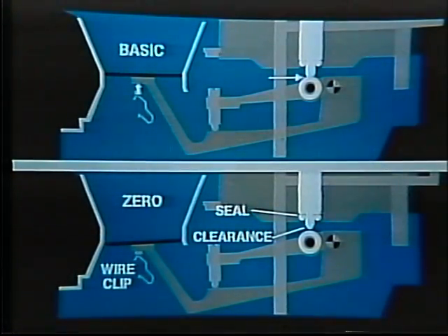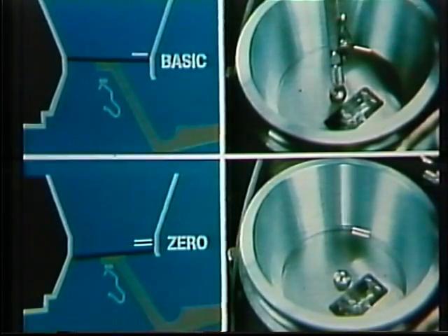In the basic position, the roller just touches the plunger. It's important the sensor plate can move a few millimeters from zero before touching the plunger. Any further movement lifts the plunger off the O-ring seal. The clearance shows in this updraft KE air funnel. Below the funnel is a straight cylinder section shown by the two lines. In the zero position, look for the plate near the bottom of that cylinder. When it's lifted to the basic position, look for it near the top, where the funnel meets the cylinder.